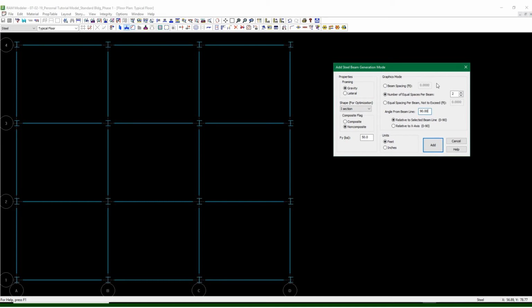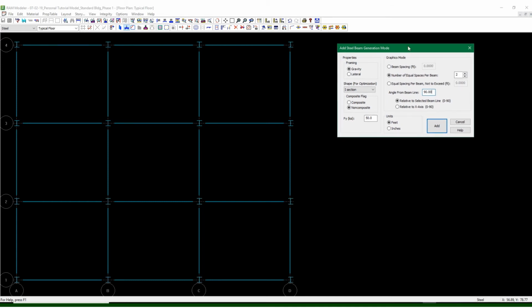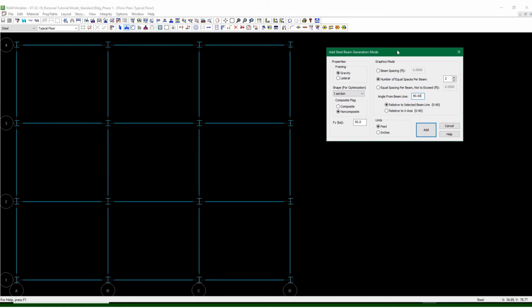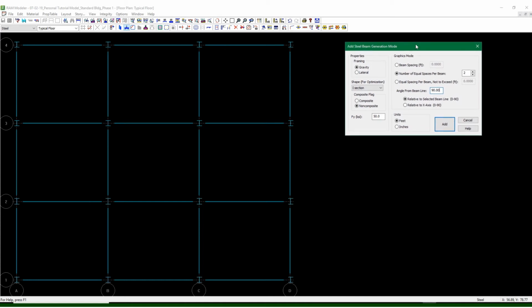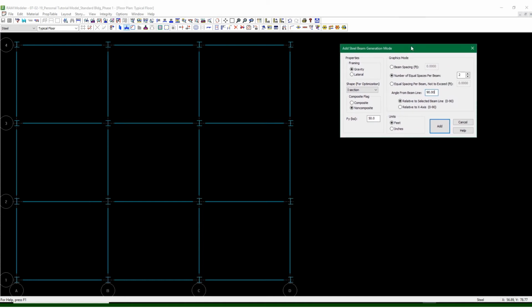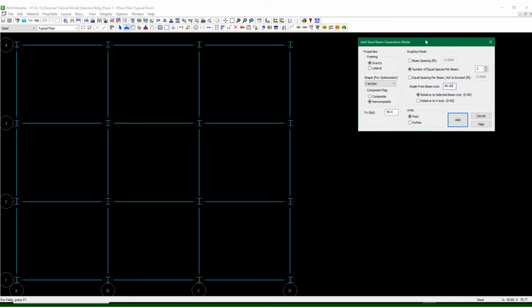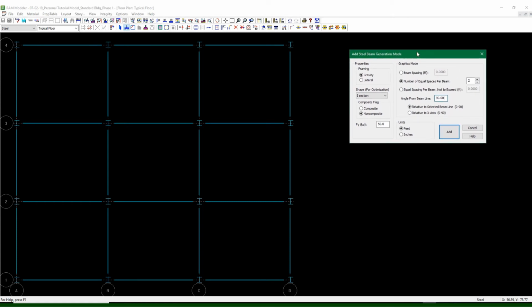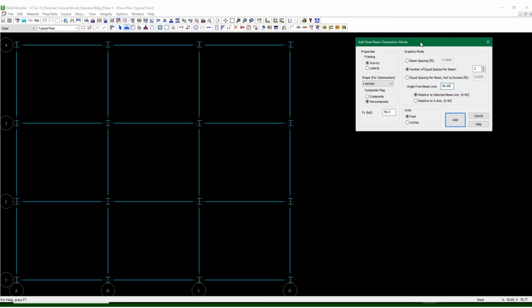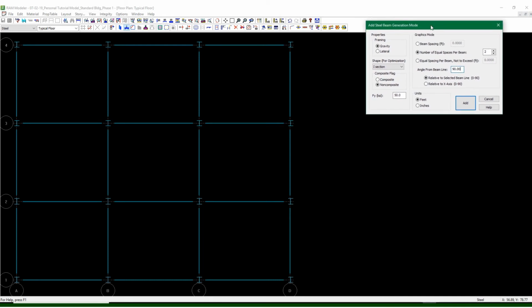So I'm going to use 5 feet spacing for this particular bay area because this particular model will just be a one-story building and roof metal deck will be used, and I typically space my roof metal decks at about 5 feet spacing maximum, just because that tends to work out pretty good for construction and design.